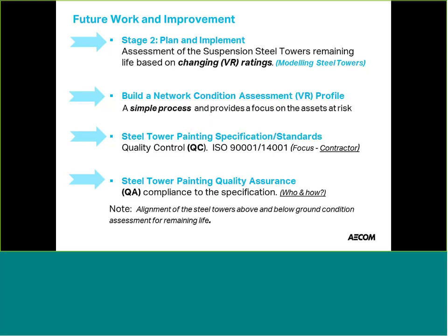Naturally, the QA system would be implemented. Who does that? Utilities love doing it themselves. They might well pay to bring in an independent party to do a QA on that contractor. That's not normal core business, if you like, for a utility that's traditionally doing power areas. There's structural integrity and the QA required on the contractor. Naturally, you would do an audit. There might be 1 in 10, could be 2 in 10. And of course, if the contractor's not up to scratch, then you make them do 3 in 10. All of a sudden, you're starting to inspect 1 in 5. And you put those costs back on the contractor. So a quality job will be the right drivers on a contractor, you get the right results.